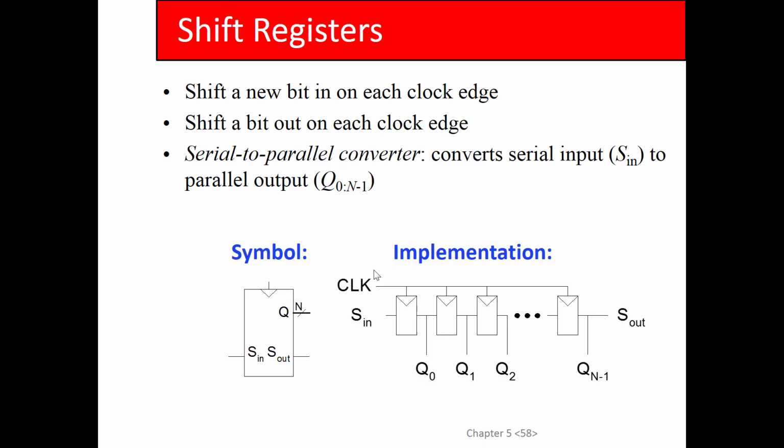Another common thing you see are shift registers, which is where you have a set of 1-bit flip-flops, and they are connected serially. So the Q output of each flip-flop feeds into the D input of the next one in the line. The leftmost one has a 1-bit input, and so every cycle you can feed a new value into the first flip-flop, and then all the other values get shifted down by 1.